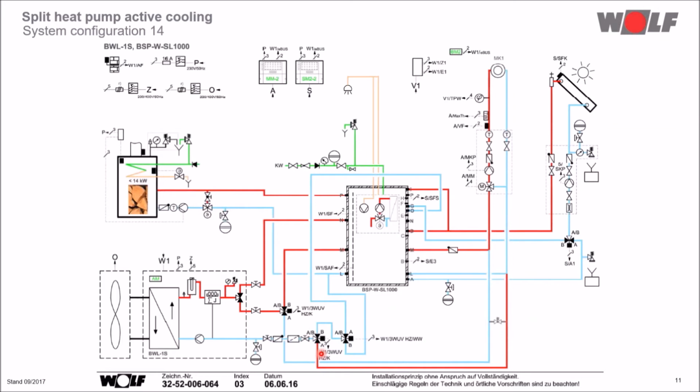The heating circuit is regulated by the mixer module and a mixer. In the cooling function, the mixer is completely opened. The flow temperature isn't regulated by the mixer. The heat pump regulates the flow temperature.